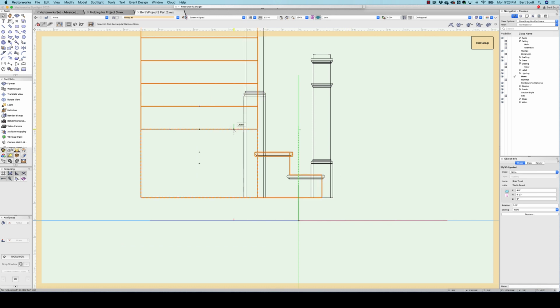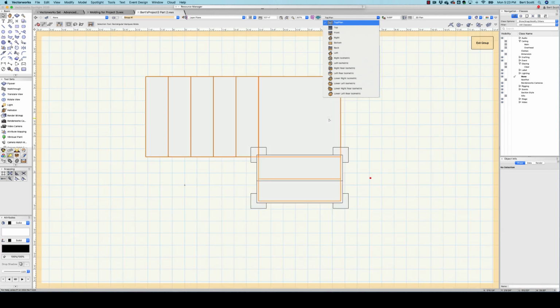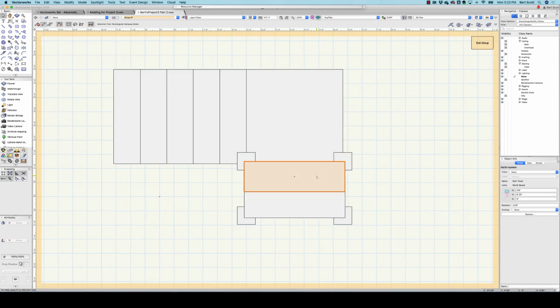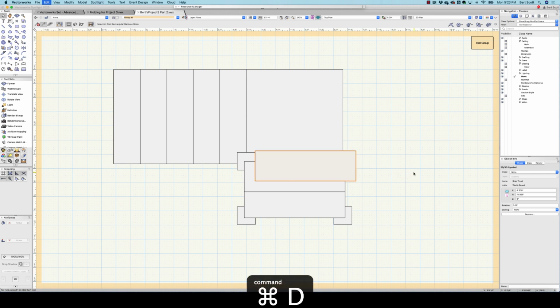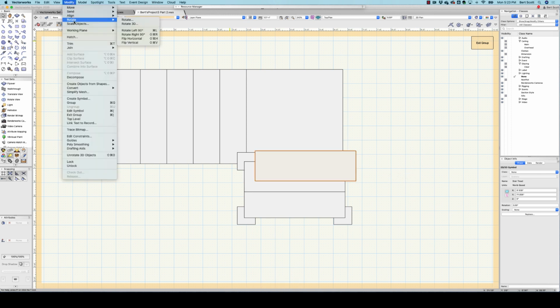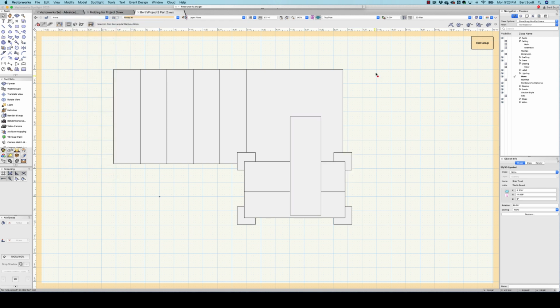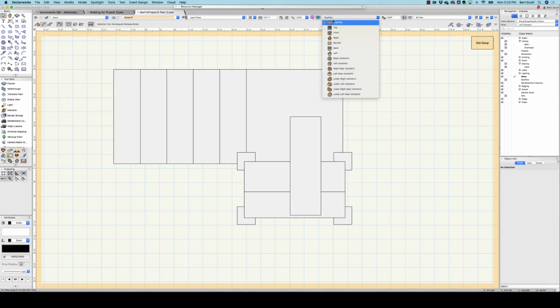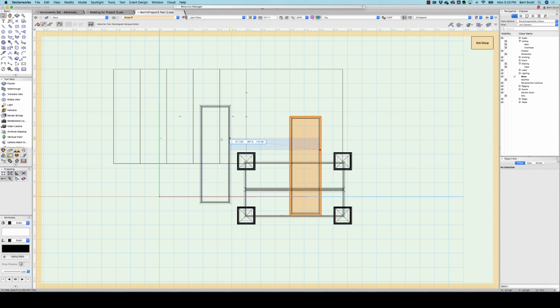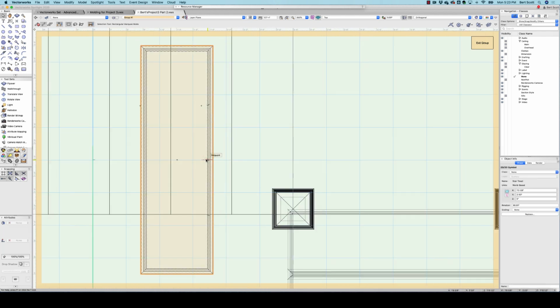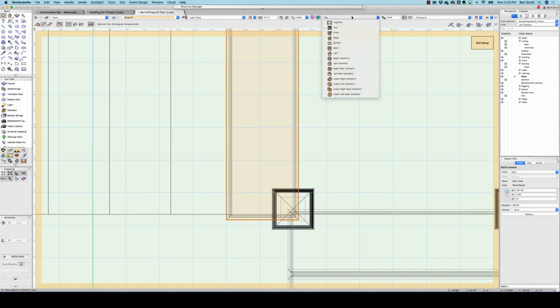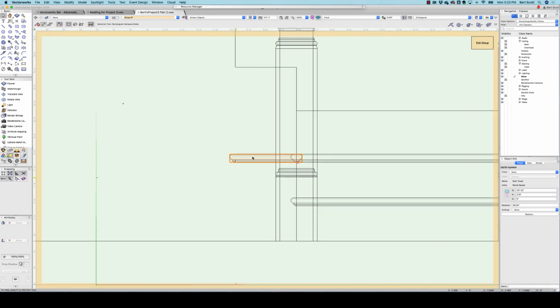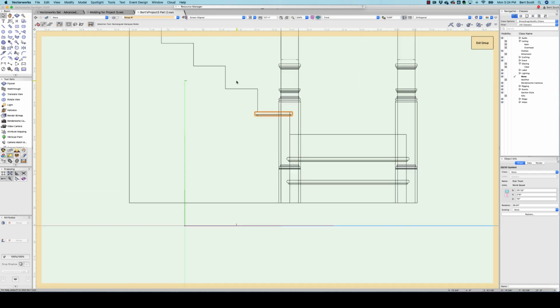The next step is a landing. It's a special case, so we'll have to create a different tread for that. So I'm going to go back to top plan view, and I'm going to duplicate the step and then Modify, rotate it to the left, and back to top view so that I can line this up, the center of it, the midpoint, with the midpoint of that step, back to front. And I'll move this up so that it lines up with the top of the actual step.